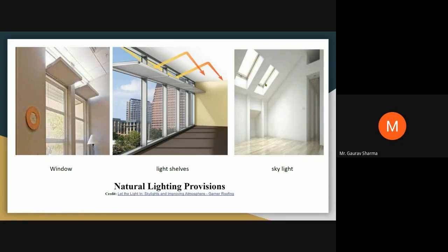So providing these windows, this kind of openings in the south direction will introduce direct heat plus illuminance. That means the glare. The glare we have to avoid always, but we require diffuse lighting over there. Most of the time, the diffuse lighting in the northern hemisphere you will be getting from the north direction. Okay, so it is as simple. Because you want to entertain the diffuse lighting over there, that's why the opening of this kind of facility should be in the northern direction.